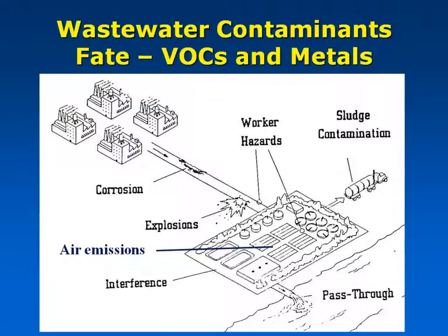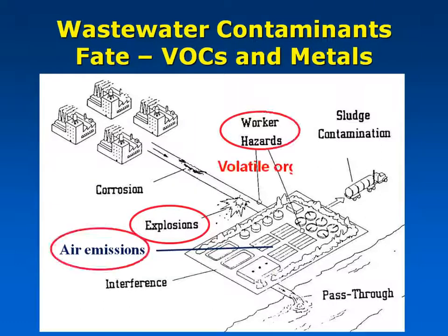So the summary of the way that Toxchem deals with these particular systems is it looks at volatile organics for places where we can predict the mass transfer of those air emissions for the purposes of not only evaluating how much or what kind of mass transfer we have to the atmosphere, but also for worker hazards, places where there may be enclosed systems. We can model these tanks with a lid on them as a closed system, and you can get a prediction of the headspace concentration if that's relevant to predicting whether there's an explosive limit being approached.